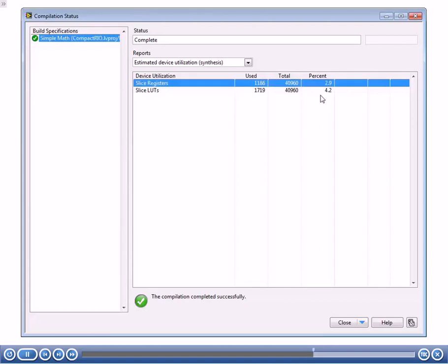One thing I want to say about the percentage though: if the percentage is at 50%, it doesn't necessarily mean that if you double what you have, it's going to reach all the way to 100%. The way that the Xilinx compiler works is as it gets closer to full, maybe 90% and higher percentages, it'll start working hard to make things more optimized.